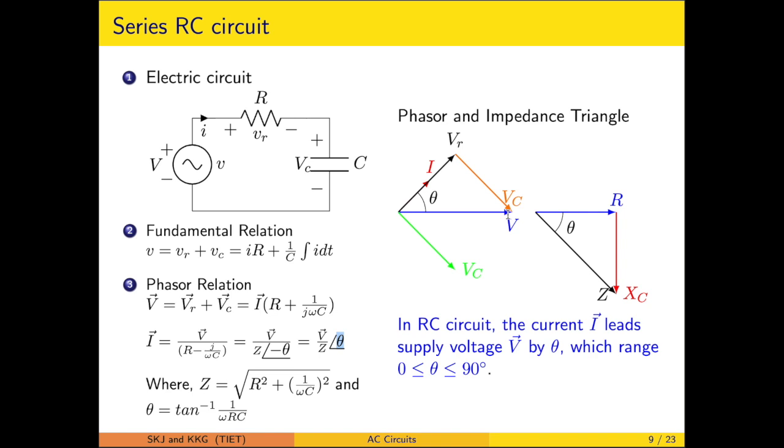On the impedance triangle, we will make use of these relations. The resistance comes out, X is downward, and pertaining to this the theta angle will be negative as mentioned here. Here also we have to keep in mind that the theta value lies between 0 and 90 degrees.